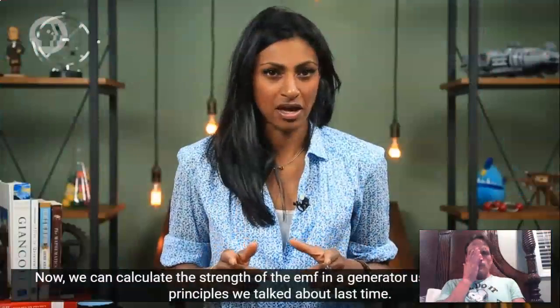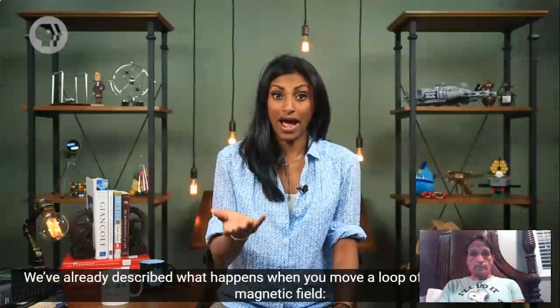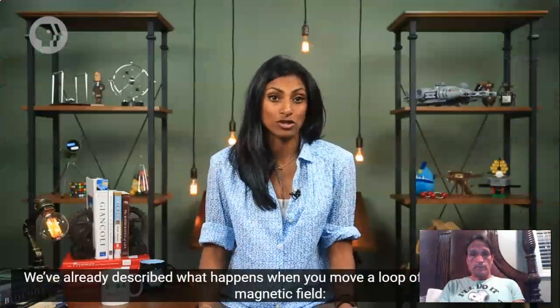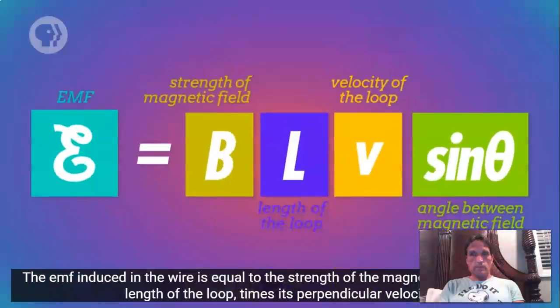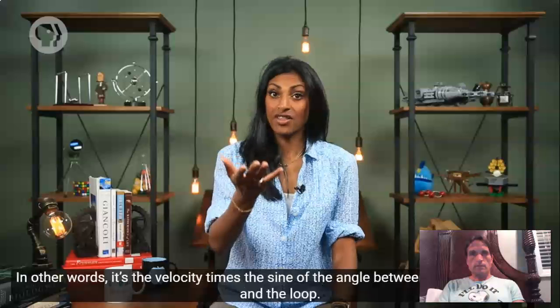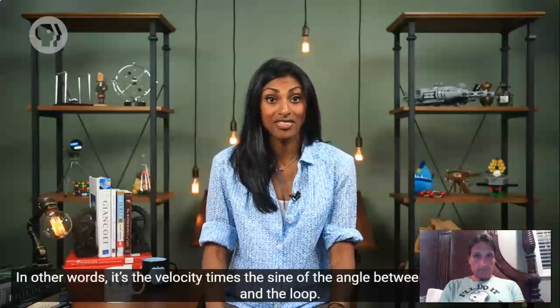Now we can calculate the strength of the EMF in a generator using some of the principles we talked about last time. We've already described what happens when you move a loop of wire in or out of a magnetic field. The EMF induced in the wire is equal to the strength of the magnetic field times the length of the loop times its perpendicular velocity. In other words, it's the velocity times the sine of the angle between the magnetic field and the loop.